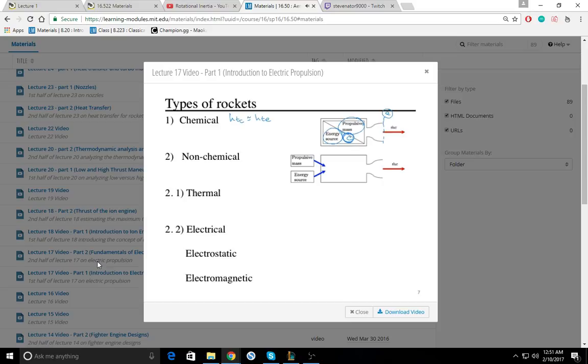So basically, this is the thermal energy, Cp Tc. And at the exhaust, the temperature drops significantly, so this is primarily the kinetic energy, 1/2 of c squared. So the exhaust velocity is approximately equal to the square root of 2 times the specific heat at constant pressure times the combustion temperature.